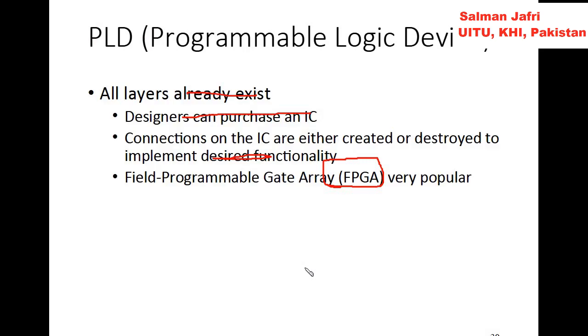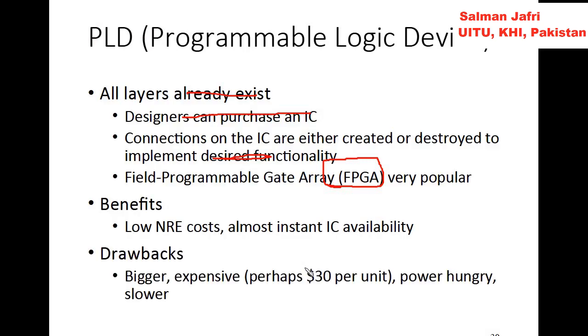Now we come to the PLD, programmable logic device, which is one of my favorites as well. In this, all layers already exist, so you can't do any customization in the structure of the IC. It is already built. So what do we do then? The connections between the ICs can either be created or destroyed to implement desired functionality. The low end examples are PALs and GALs, right?